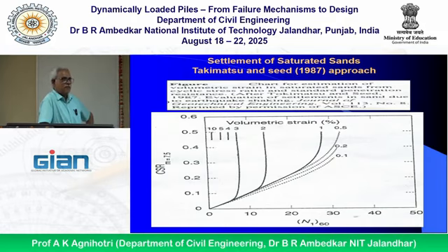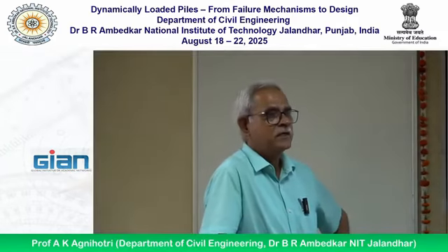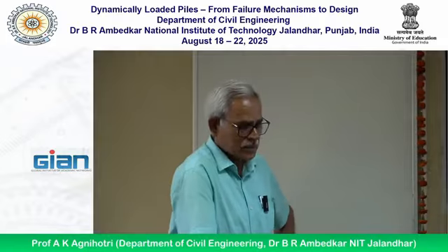N160, you have performed SPT, you have N160, you have CSR M7.5 as we have calculated earlier, liquefaction potential based on SPT. CSR M7.5 you have calculated value, N160 you have value corresponding to these two. Suppose your point lies here. So approximately we can calculate volumetric strain. So that volumetric strain multiplied by thickness of sand layer, that will give you settlement.